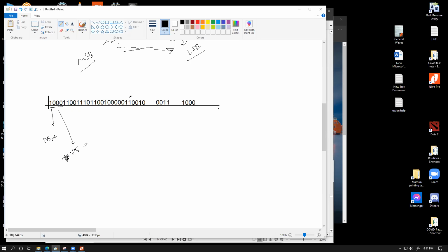375. So for 375 microseconds, the light source would be completely off. This 375 microsecond should not be read as 1. On the receiving end, it will read off this 375 microsecond darkness as 3 zeros, because it would know that it is supposed to read every 125 microsecond as one single piece of bit.